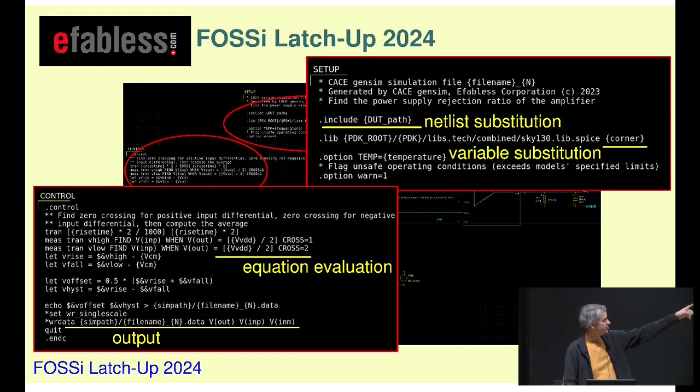Likewise, if you need equations, for instance, I have added equations to ngspice where it otherwise can't do them, such as I want to measure where the output signal crosses 1/2 VDD. So I just put in VDD over 2, and whether I'm simulating at VDD or VDD plus or minus 10%, it will calculate out the half value.